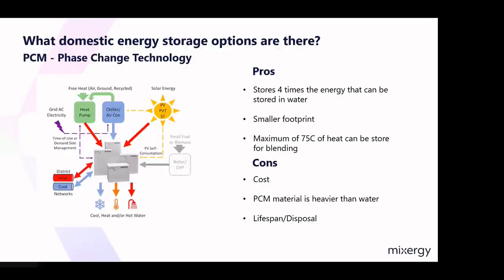Energy can be added in the following ways: solar thermal energy via a liquid flowing through a heat exchanger, which is most efficient; electrically generated from solar PV during the day or cheap off-peak electricity; or from a heat source like a boiler or a heat pump. Heat can then be extracted as hot water to outlets or as space heating via radiators and underfloor heating systems.